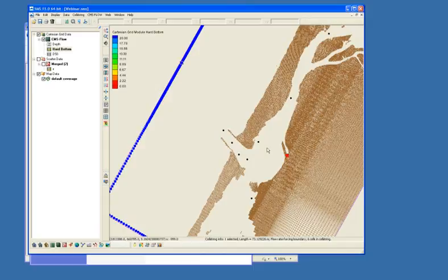But in some places you don't want it to be able to erode that far. Like in Florida, there's a couple of different inlets. One of note is Sebastian Inlet, where throughout the entire inlet throat and back into the back bay there's a rock at the bottom, and you need to model that. And so they have taken some sand samples and figured out what those depths are for the most part, and been able to set some values out here.